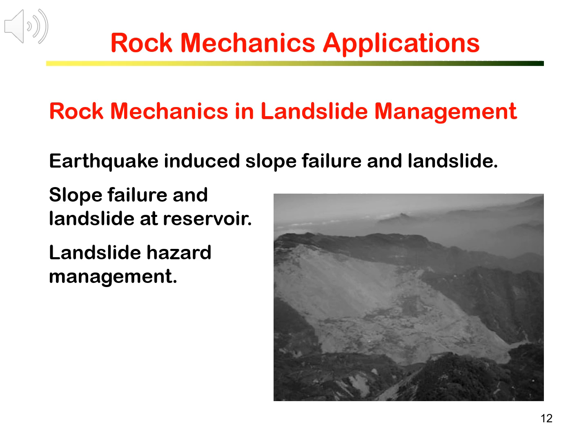We're also very concerned with slope failure and landslides at water reservoirs due to water level fluctuation. The changes of water pressure in a slope may cause the reservoir slope to be unstable and to fail.